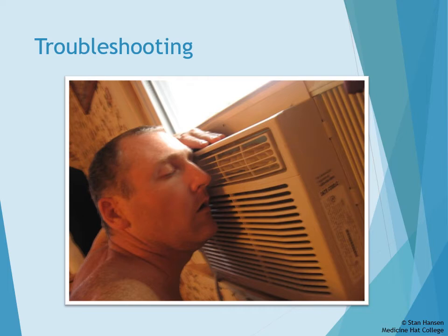Go outside to the air conditioning unit and check to see if you have the proper line voltage going into the input of the power relay inside the air conditioner. If you don't have voltage there, it could be the disconnect is off. If you do have proper voltage there, check to make sure that both the compressor and the fan unit are in proper working order by visual inspection.